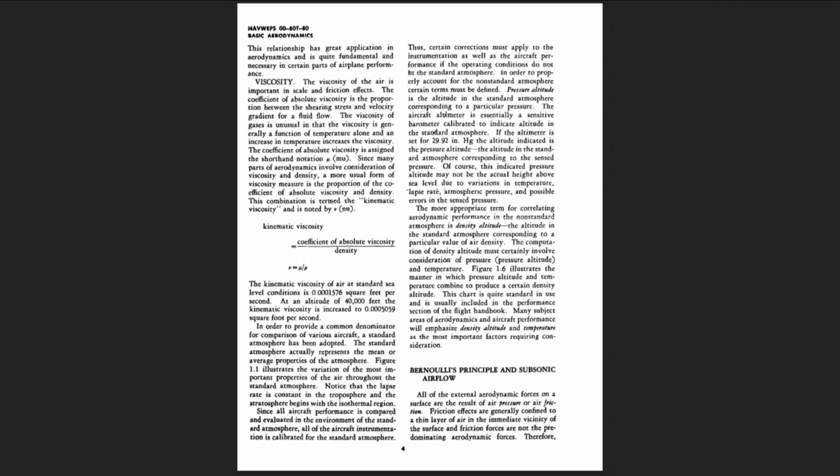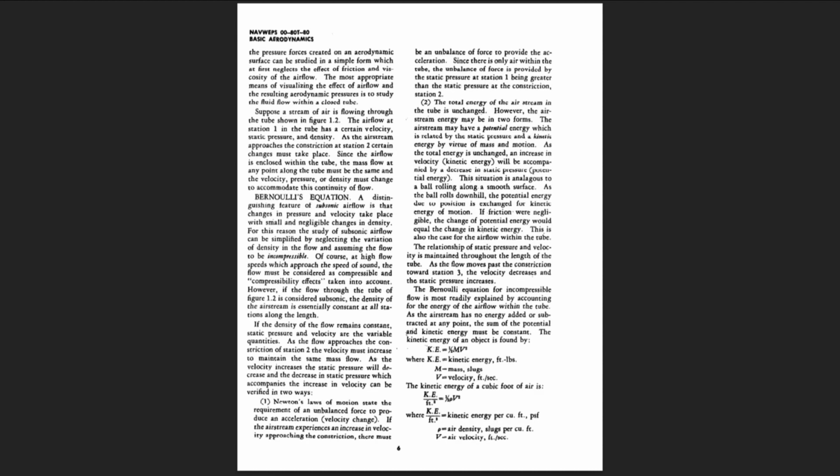Bernoulli's principle and subsonic airflow. All of the external aerodynamic forces on a surface are the result of air pressure or air friction. Friction effects are generally confined to a thin layer of air in the immediate vicinity of the surface, and friction forces are not the predominating aerodynamic forces. Therefore, the pressure forces created on an aerodynamic surface can be studied in a simple form which at first neglects the effect of friction and viscosity of the airflow.